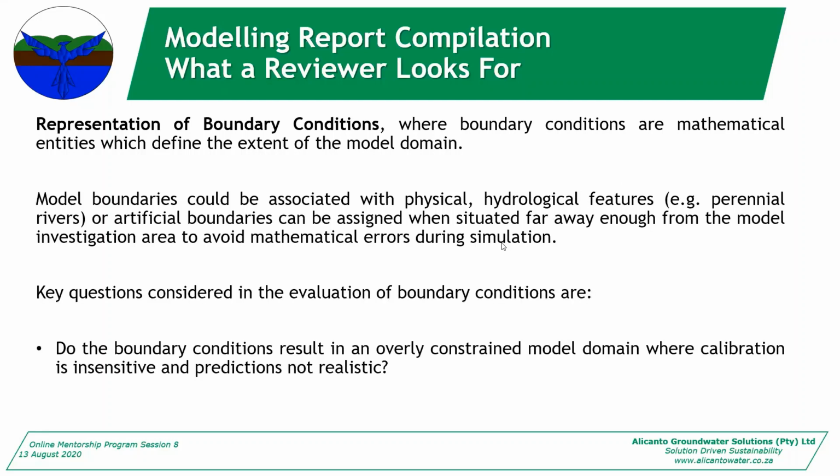Your key question when we evaluate the boundary conditions is, do the boundary conditions result in an overly constrained model domain where calibration is insensitive and predictions are not realistic? So have you made your model domain too small? Have you made it where nothing affects anything else? Your numerical model has become an analytical model, and then your predictions are meaningless.